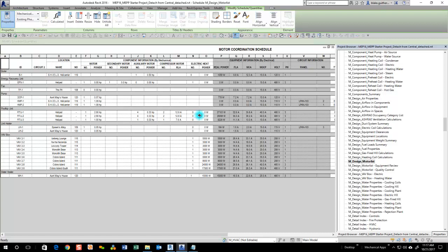So that ultimately is what determines full load amps and minimum circuit ampacity, which then can be used to determine MOCP. So we are able to get electrical information a lot sooner, and then they can choose to use it or override it. But then they have the information up front.